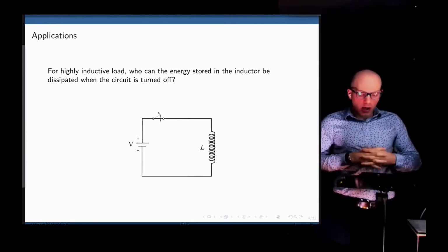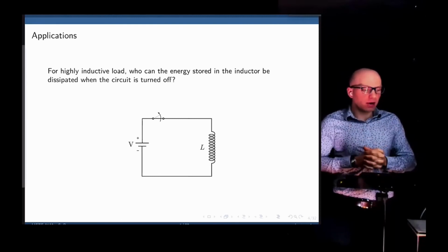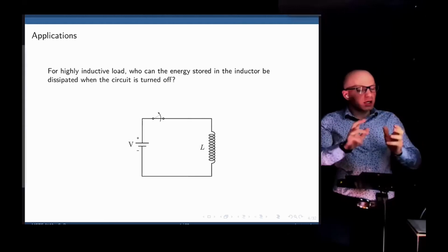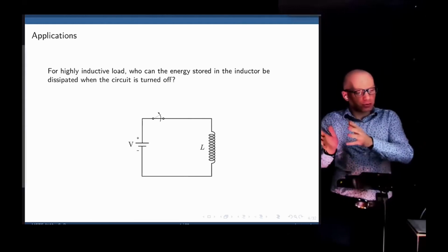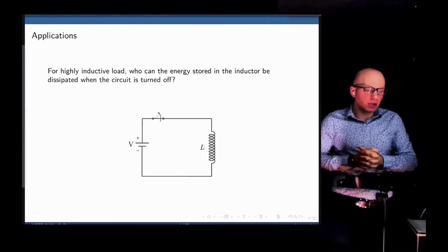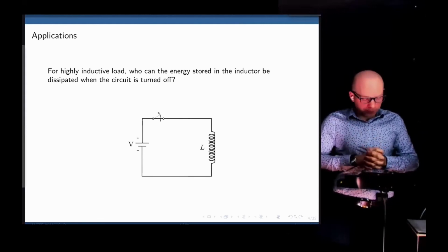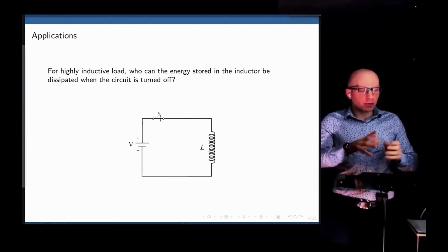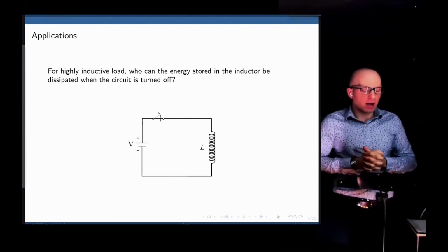Right? And this is a problem when you have, let's say, a high power system connected to a low power system, such as a microcontroller. We don't want any of that energy to be flowing into the microcontroller and destroying the low power side. So we need to use a diode somewhere here to prevent this energy from flowing back into the system.